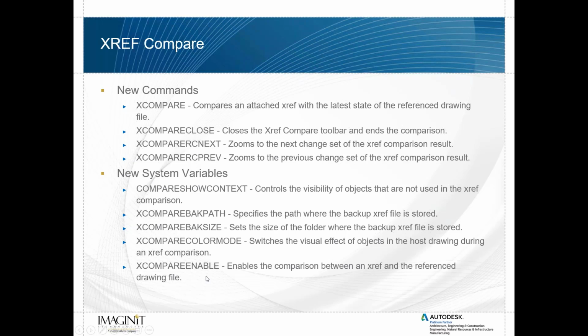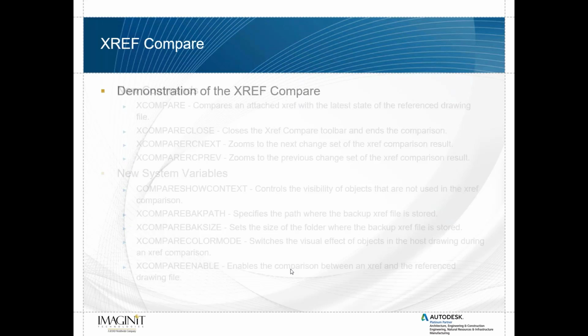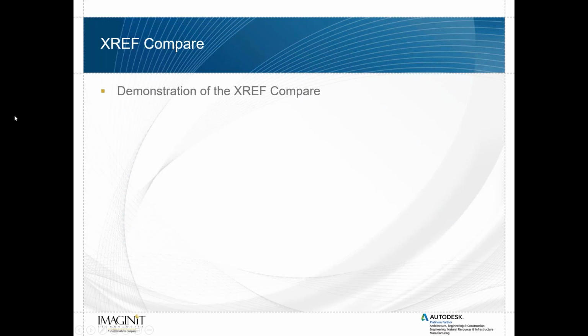New system variables here: one controls visibility of objects that are not used in the XREF comparison, one specifies the path where the backup XREF file is stored, and one sets the size of the folder where the backup XREF file is stored, etc. Right, another switches visual effects and enables the comparison between an XREF and the reference drawing file. So let me go ahead and show that.